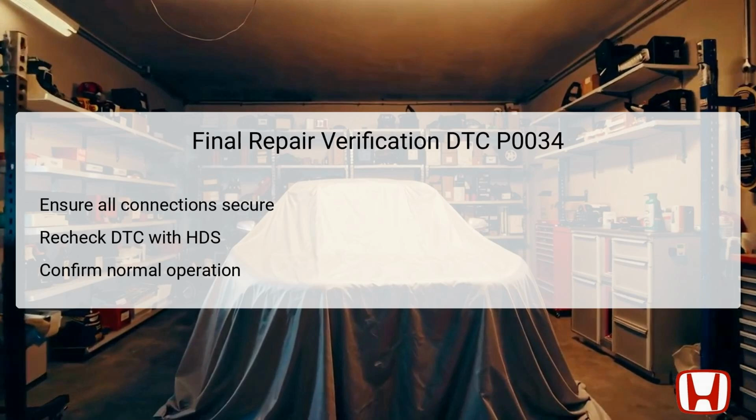Begin by ensuring that all electrical connections involved, particularly for the turbocharger bypass control solenoid valve, are secure and properly assembled. Use the Honda Diagnostic System, HDS, to recheck for any stored diagnostic trouble codes. Monitor to confirm that DTC P0034 does not reappear after completion of the repairs. Additionally, take the vehicle for a test drive to verify normal operation of the turbocharger and engine performance.